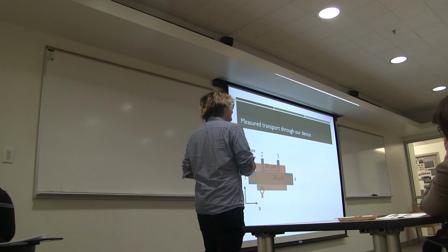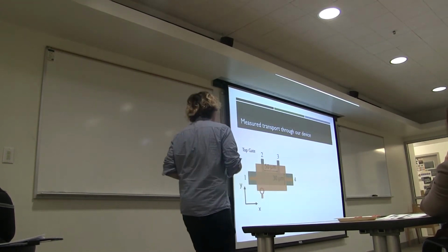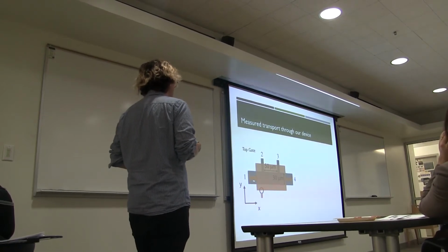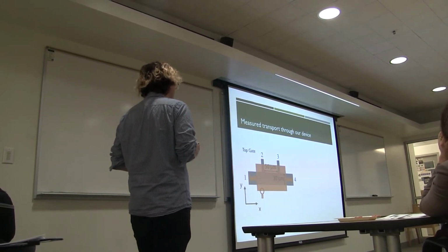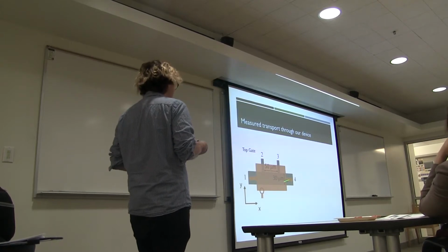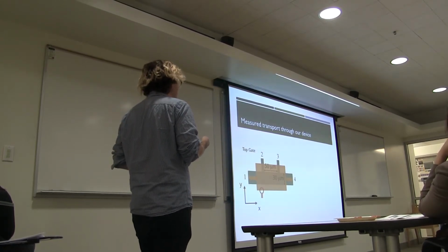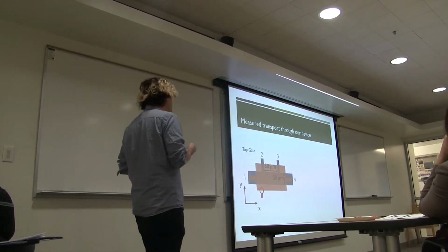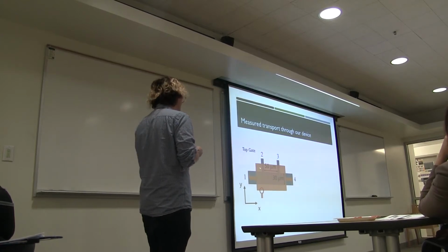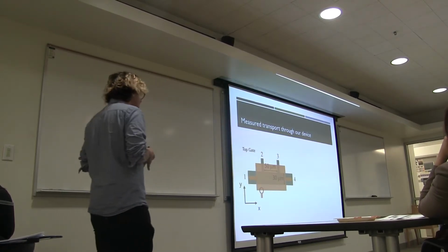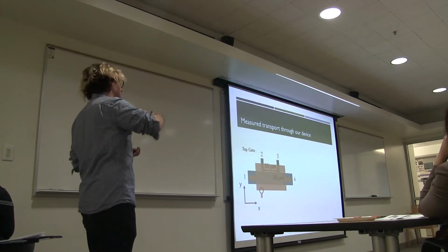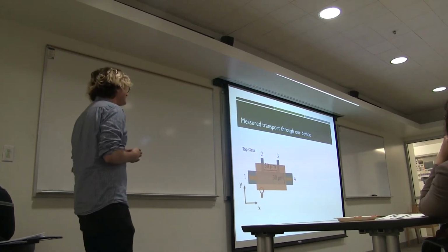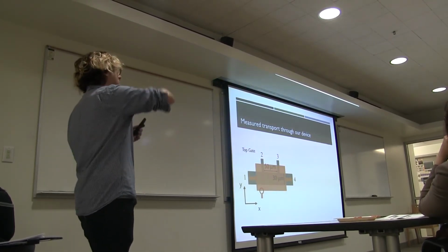So now that layer profile I showed you is going into the board, and our collaborators use lithography techniques to pattern a device for us. So these are all connected to gold contacts. We flow a current from the left side to the right side, and we can also probe the voltage of the device across these 2 and 3. The other feature of this device is that there's a gold top gate, which is not electrically connected to the device, and this allows us to tune this Fermi energy. So initially this material is actually n-doped, so its Fermi level lies in the conduction band, but with an electrostatic gate we can tune it so it's in the insulating regime.